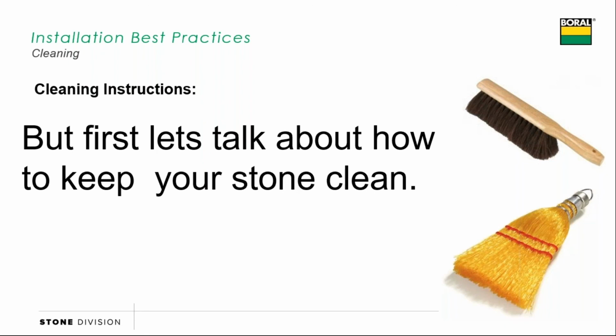If you're using a conventional type S or type N, a little bit of mortar splashes or smears on a stone, if you let it sit for about a half an hour to an hour, depending on the temperatures and all that, it starts to turn white and you can brush it off immediately without any negative effect left behind. If you wait until the next day, it will leave a stain and you're not going to be able to get it out.